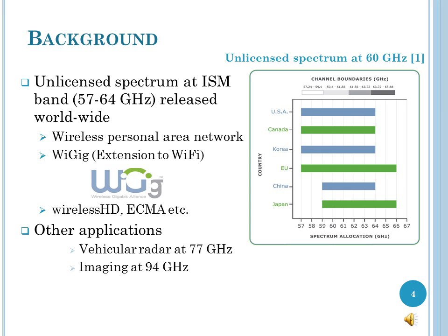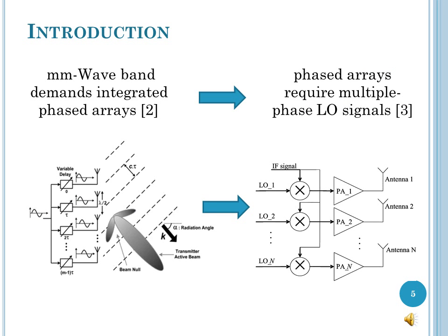In addition to obtaining high speed systems, the added advantage of moving to higher frequencies is the reduction in the size of the antennas, as wavelength is about 2.4 millimeters in silicon dioxide at 60 GHz. Thus, compact systems can be created, but the small size of the antennas necessitates highly directional beams for communication, which could be obtained using techniques such as phased arrays. This is also suitable as the behavior at V band is more line of sight and there is less diffraction